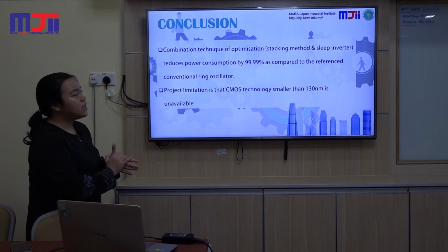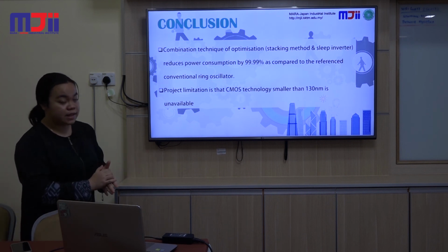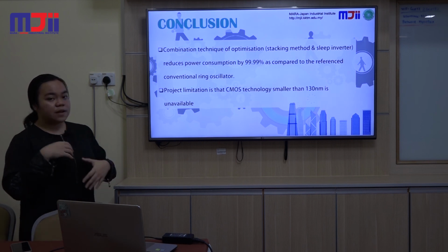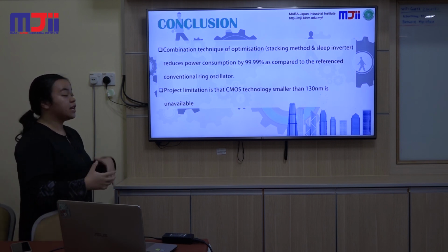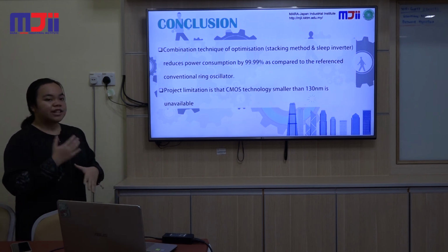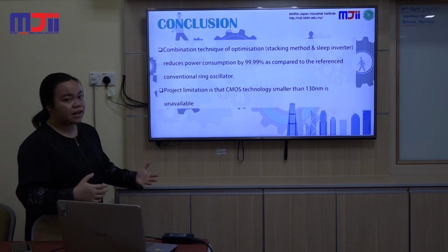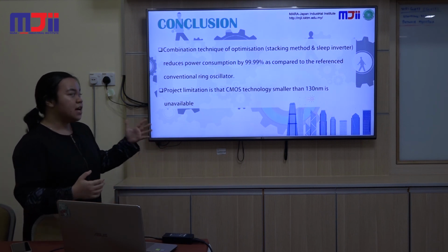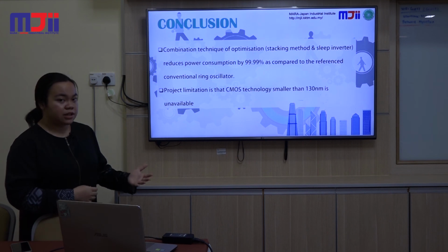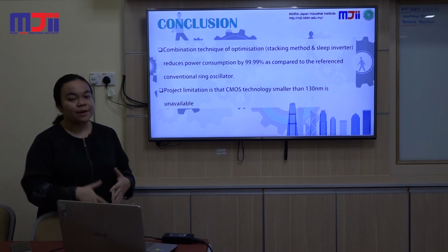Okay. So in conclusion, the technique that I've done was a sleepy stack inverter, and that was the optimization technique that I chose. It has 99.9% reduction, so that is very good. However, as I've said, there are project limitations, which is that I cannot go smaller than 130 nanometer technology due to the restriction of the simulation that I'm currently using.